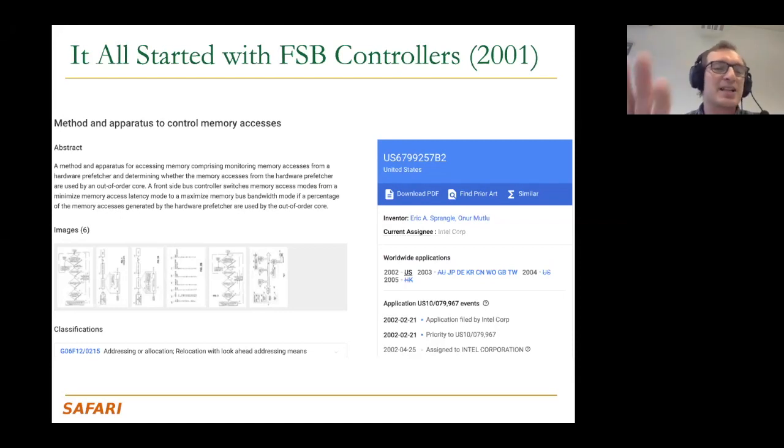There are other prioritization mechanisms in the patent. You don't need to think about that. But the core idea is really some prefetches, we know that they're good, but they're late. If the memory controller doesn't prioritize them, they'll be even later, essentially they'll be useless. But if the memory controller prioritizes them, even ahead of some demand requests, that's the interesting part, you get better performance because this prefetch will in the future lead to a demand request being eliminated. That's the idea. And this is one of the earliest works that I've done on memory controllers.